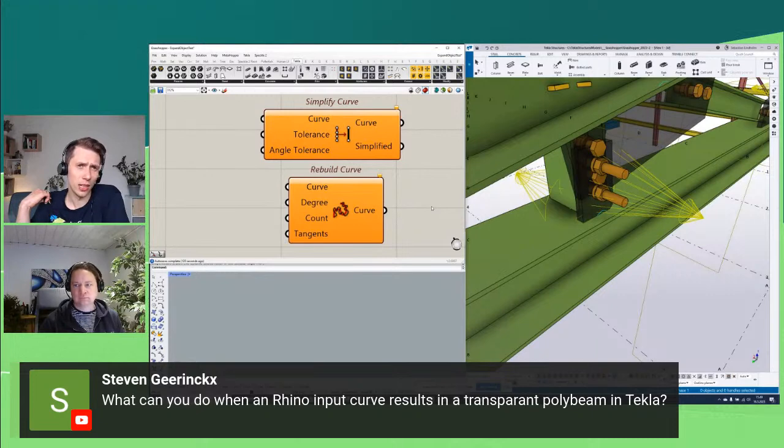Sometimes it's because some corners are too sharp, or some radii are going into each other. I've had this problem with pre-stress reinforcement, where you have lots of double curves. So actually you have to create an item, not a beam. That was the solution in some of the really extreme examples.